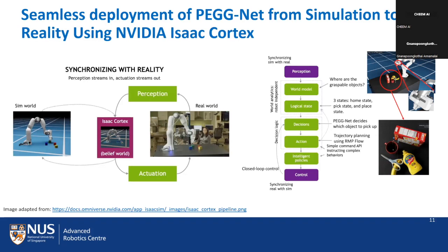So the network will first predict the optimal grasping point. So the location first. The location gets predicted first. And then based on that location, it will select only one gripper orientation, also only one gripper width. It won't output all of the gripper widths, even though you are right in saying that there can be infinitely many.